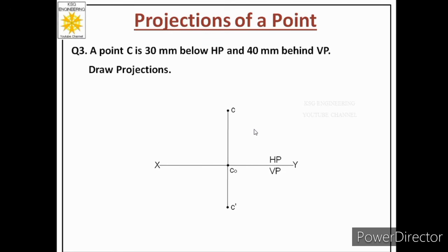After that we will place dimensions. So we will leave 1 millimeter gap, continuous thin line which is an extension line. We will place dimension line. After that we will leave 1 millimeter gap over here to draw the extension line, and we will draw dimension line. And you can see that over here we have followed chain dimensioning.